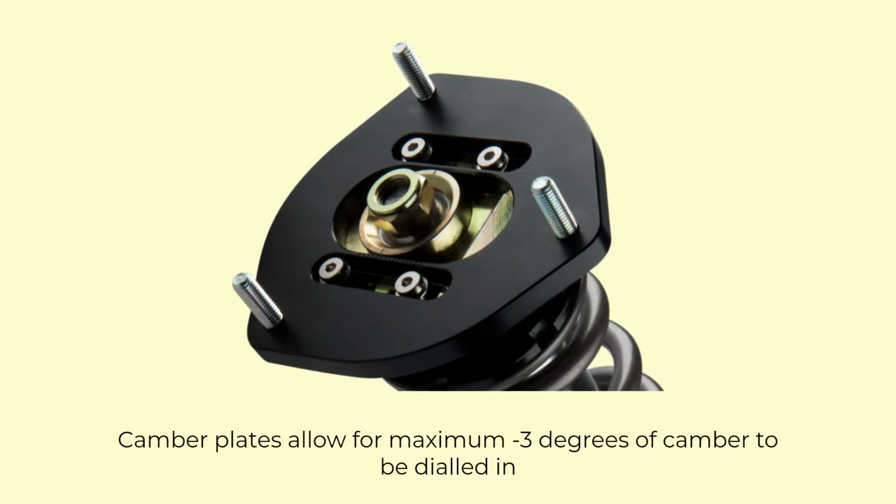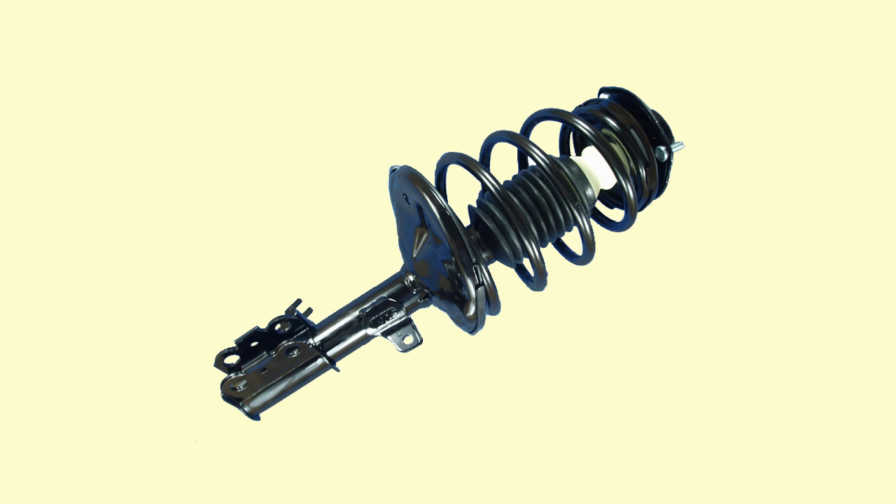If you want to dial in even more negative camber, as well as quick camber adjustment on the fly, you can use camber plates, which allow for roughly up to 3 degrees max. Whilst the installation process is a little bit more tedious, requiring the complete removal of the front strut to replace the top strut mounts with the camber plates, this allows for negative camber to be dialed in quickly via sliding the plate inwards.